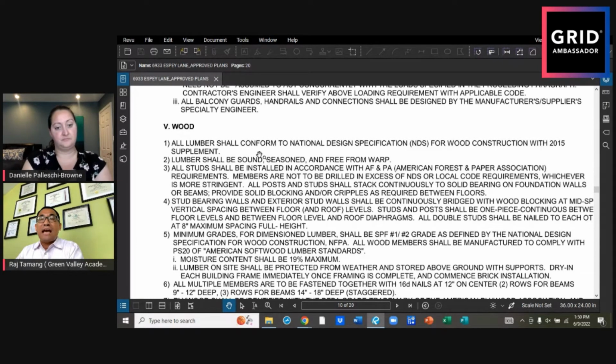Also, the load application for the patio is different because the patio is sitting on the ground, like a slab on grade. You make sure you prep the ground properly so it doesn't settle and crack. But in a garage or commercial building, you have an elevated slab, not on the ground. Those have to be properly cured before you apply the full load.